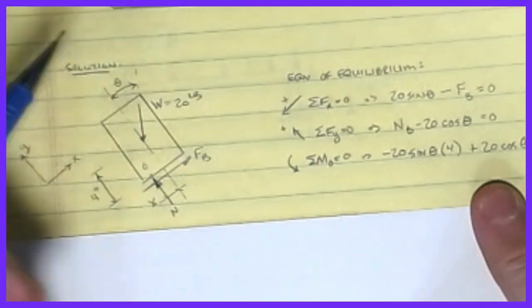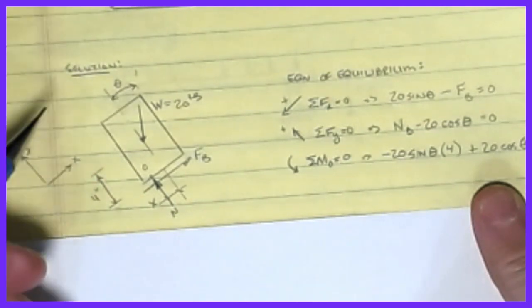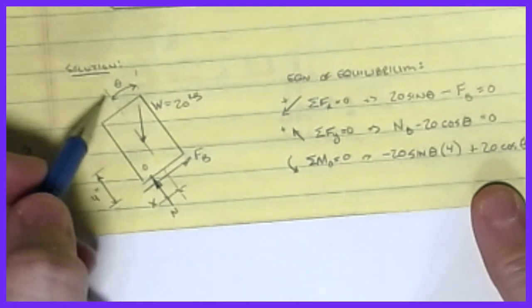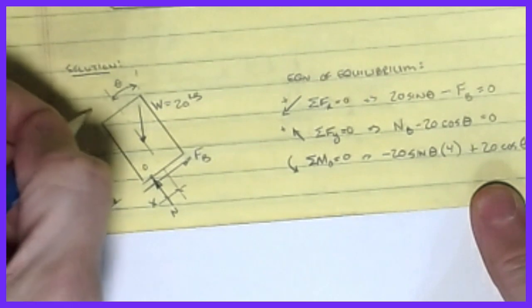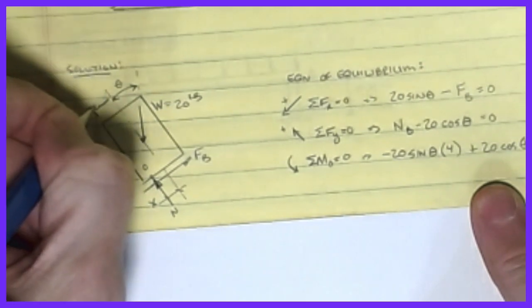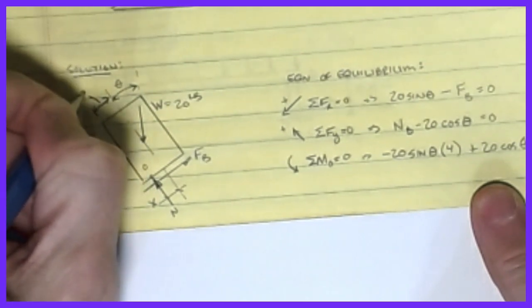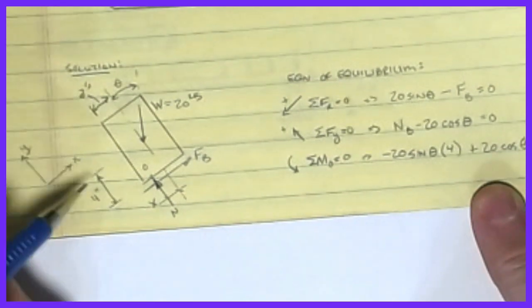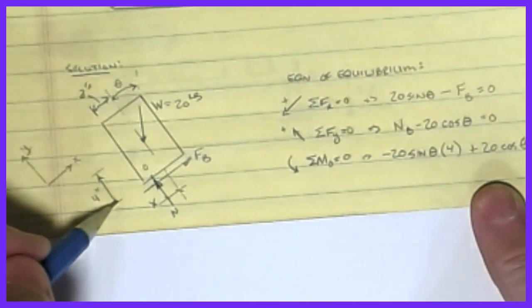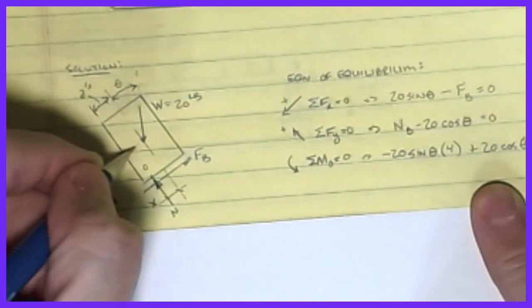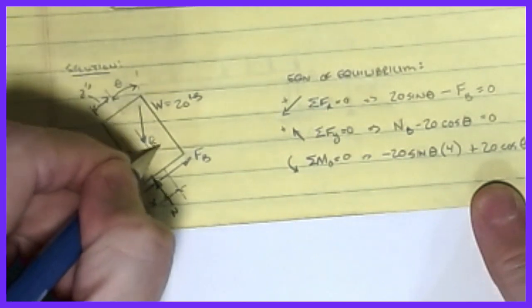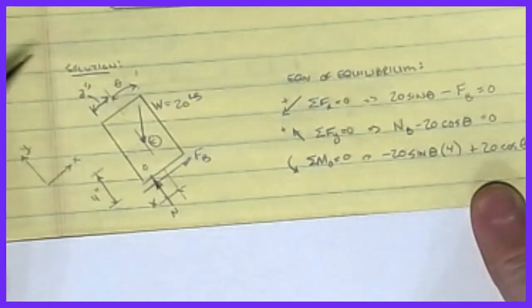And so what I've done is drawn the object. Again, we have dimensions of 4 inches and 8 inches tall, so I know that this dimension is 2 inches, and then we have the 4 inches labeled from the bottom of the object up to here, and that helps us to triangulate to where the center point or the centroid of the object is.